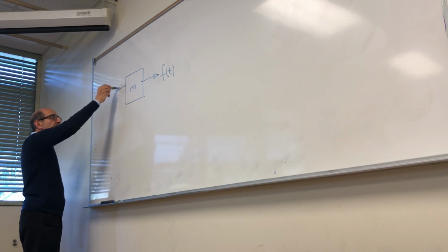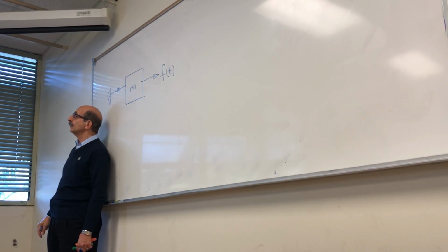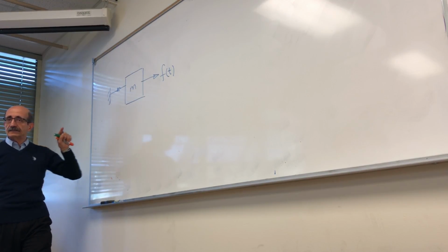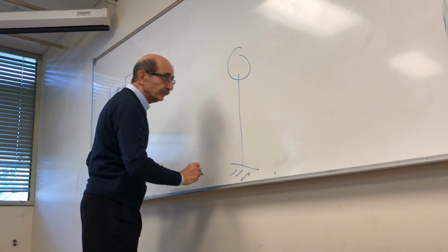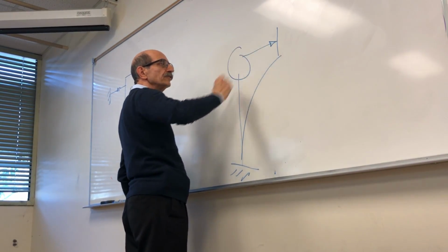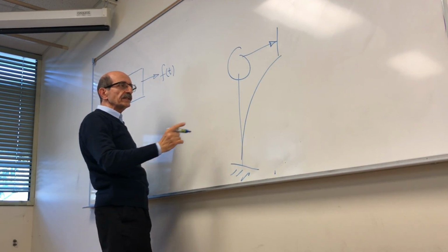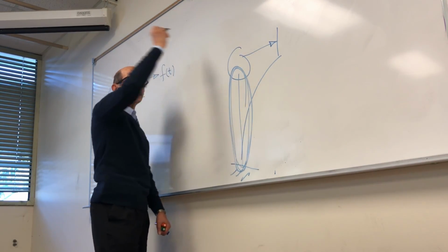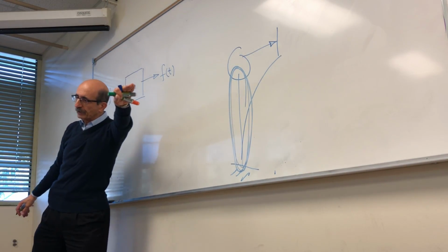One is a force that, if you assume this is linear or translational motion, is resisting the motion in that direction. Think about this. Again, going to that cantilever beam. This cantilever beam is moving in this direction, in translational direction. What is resisting it is the stiffness or the spring that this beam represents, right?